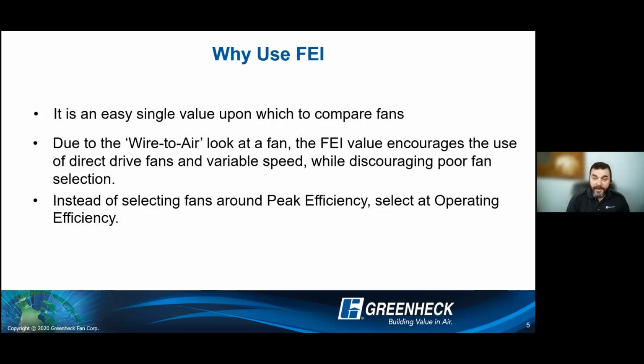Yes, I probably can. But that fan is spinning at its top end. The sound is going to be much higher. And where it's operating in its capability, the efficiency is not going to be as great. So FEIs are just naturally going to help encourage you to good selections.